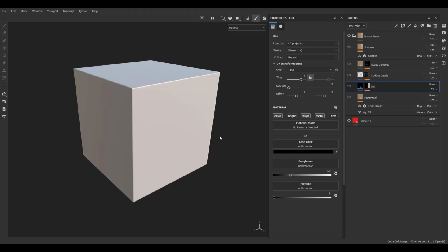So after that, when you bake there are no lines, there is no mistake on the normal and your mesh maps, okay? And for the second technique, we just put seams for the UV on the sharp edges on the model, okay?